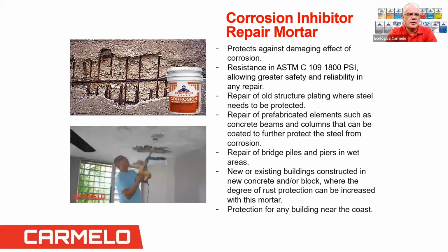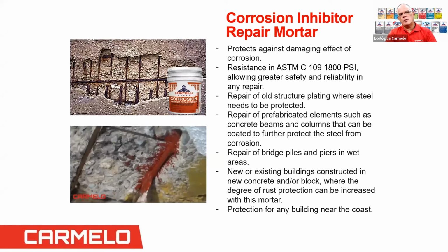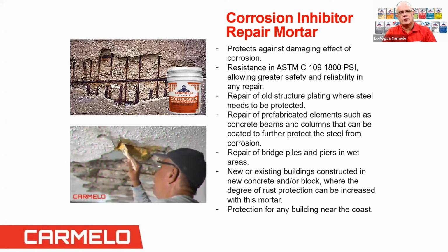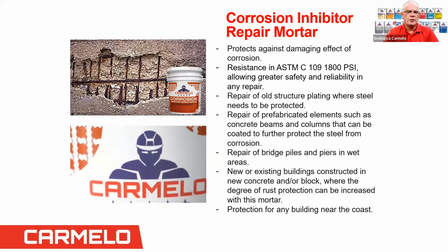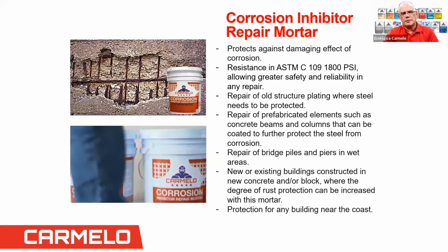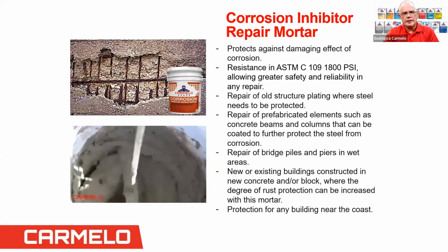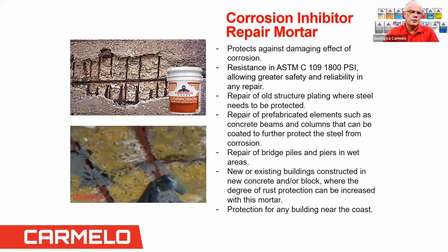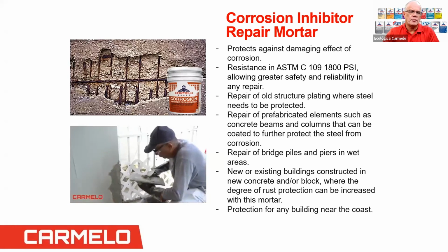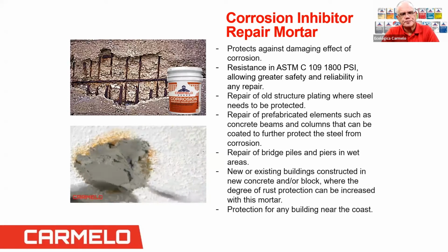Again, when the stucco came out, your rebar might have expanded two times or three times the volume, right? So here they cleaned the rebar, and they applied a coating over the rebar, and now they're putting stucco and finishing with the corrosion inhibitor.